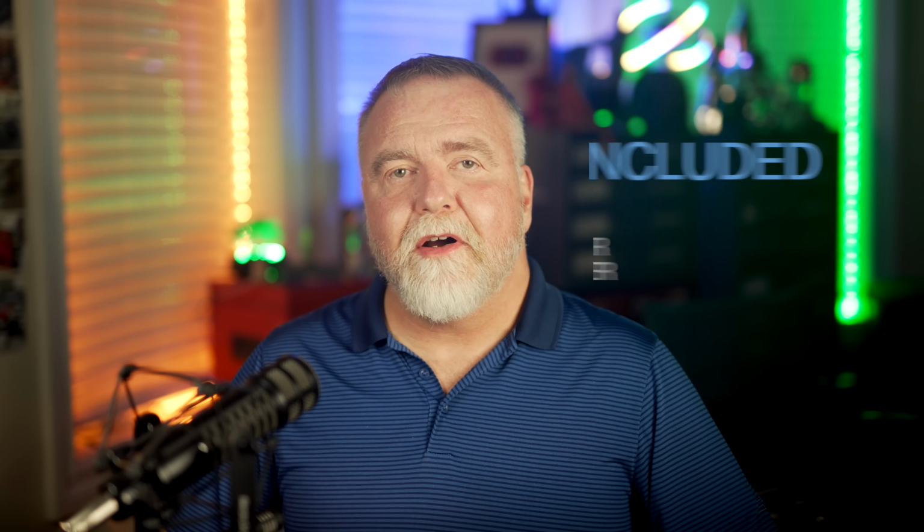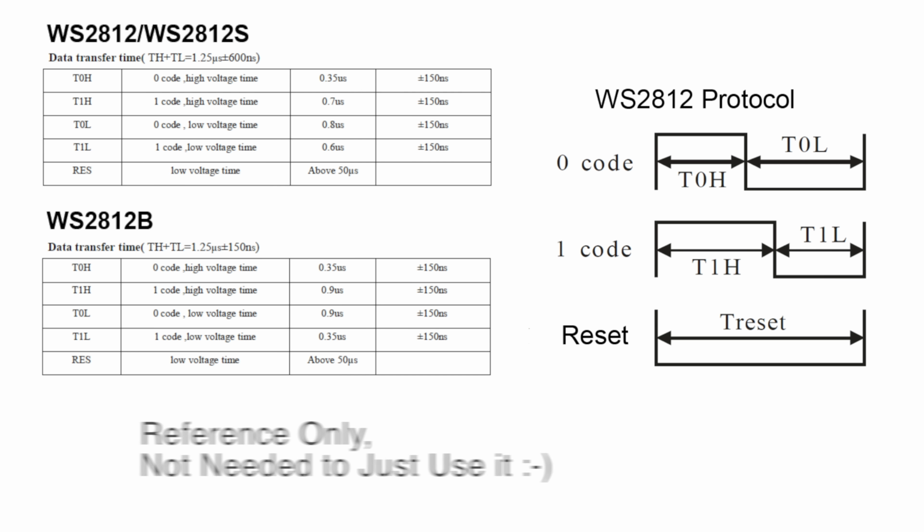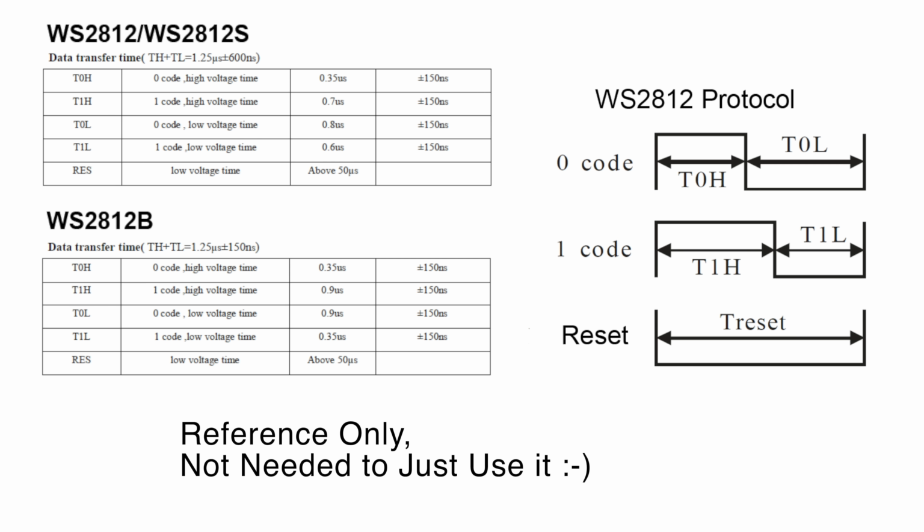Let's have a look at how the module communicates with the strip. It's going to prepare and send a square wave signal that contains little batches of 3 bytes each. Those packets contain the color data encoded in 24-bit RGB, one for each LED. In between frames, there'll be a gap of at least 6 milliseconds, and that signals the start of a new frame. Now, there's no configuration or setup to be made between the chip and the module.